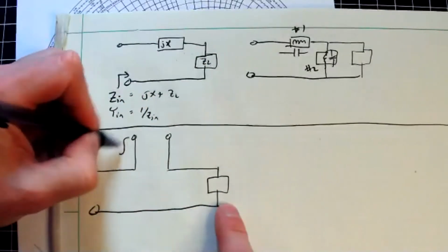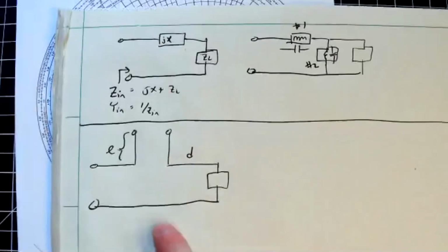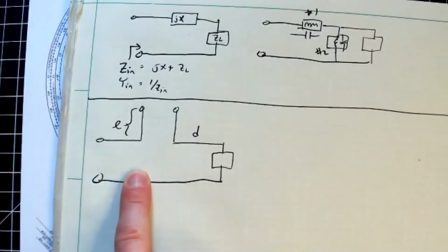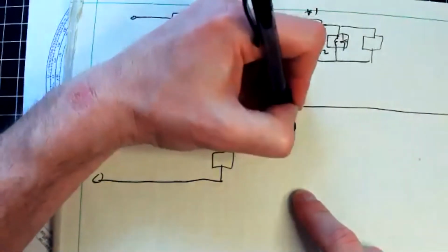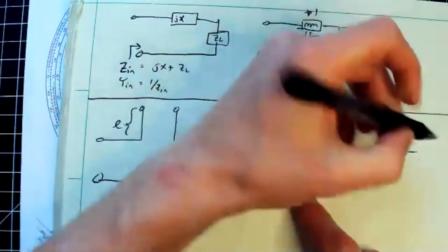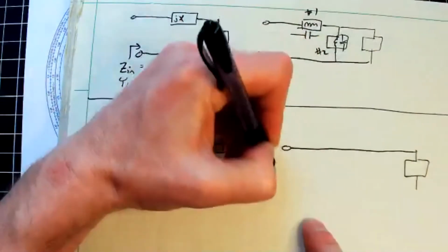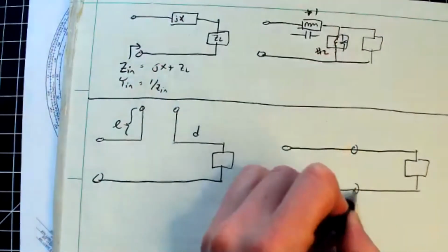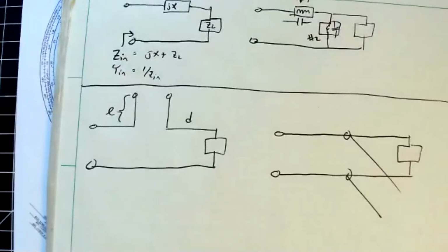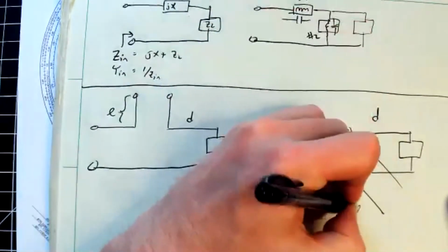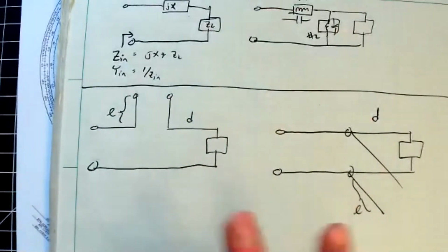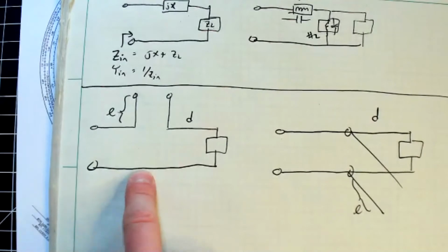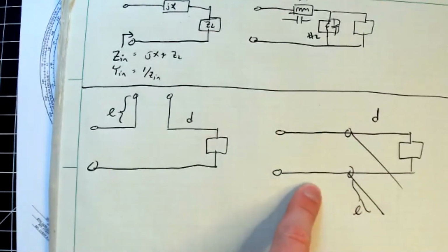So this is your length L, and this is your D. So this will have two solutions for D, which will create two solutions for L. And then this situation over here, this is the shunt stub, where we put some little length of transmission line breaking off that way. So again, this is D and this is L. So you can see there's technically four solutions you have to calculate in total, but two will correspond to the series, two will correspond to the shunt.